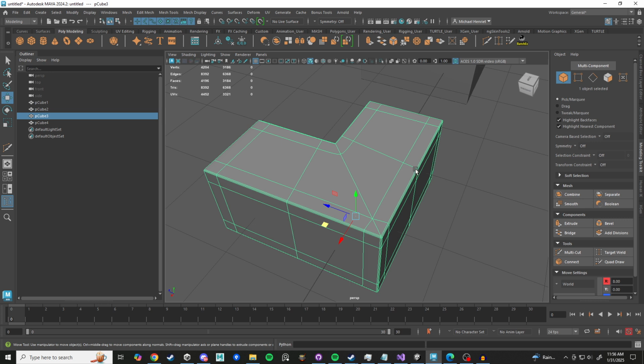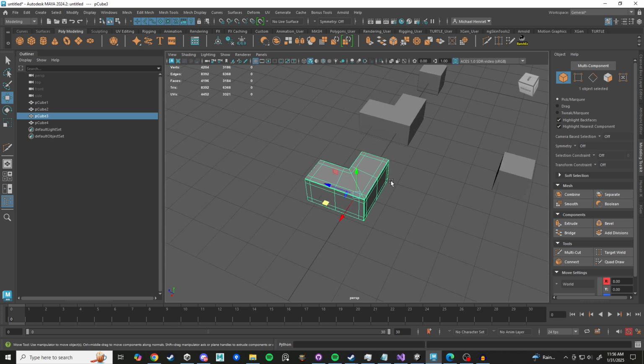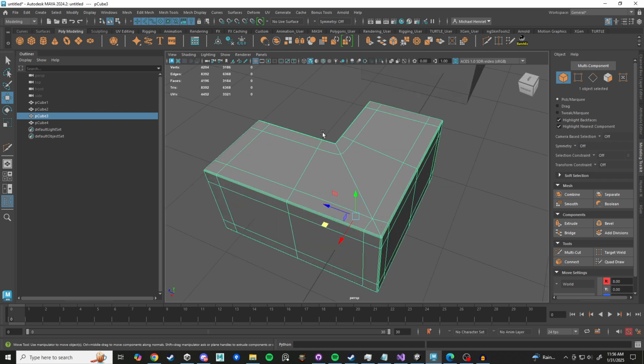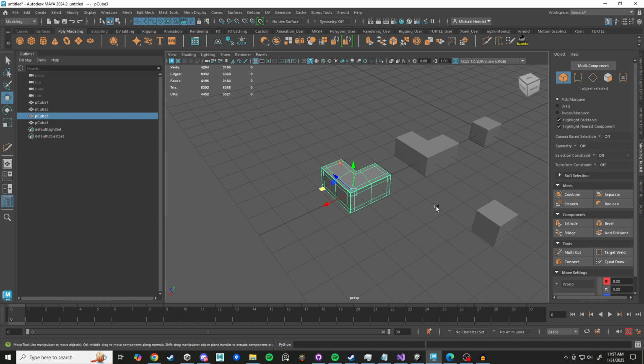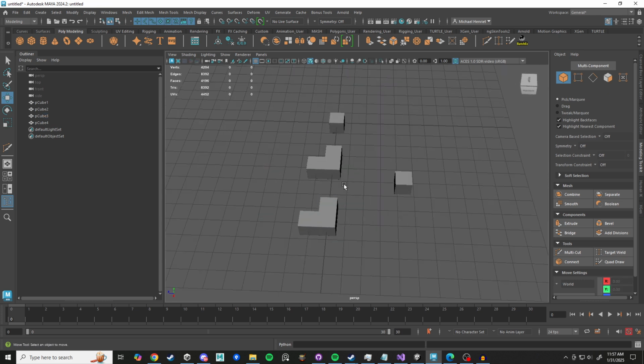So that's how you work with bevels. You have to resolve them. Don't just bevel everything. Experiment as well. You're going to use a bevel in certain shapes, because this is still pretty simple. But you're going to have some complex armor shapes, I bet, and you'll be like, oh man, this bevel didn't work. Feel free to undo it. Try something else. Try multi-cutting to simplify some shapes, terminating some of these edges diagonally or across or something. Try some different approaches. So that's bevel.